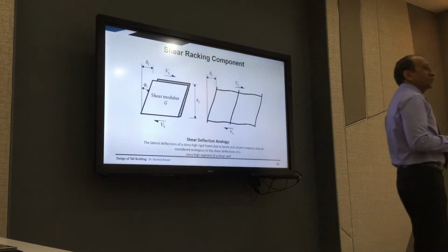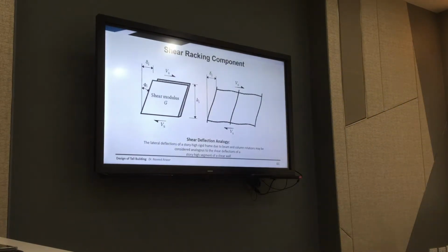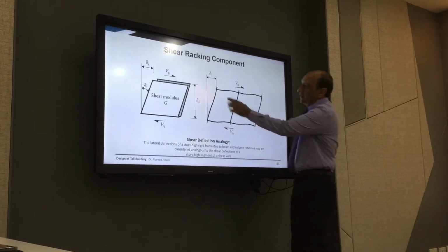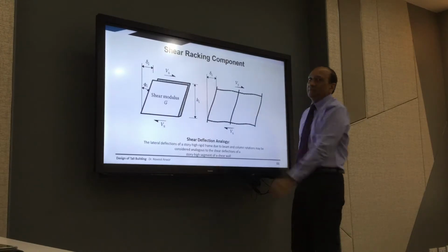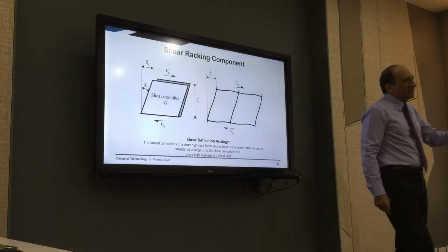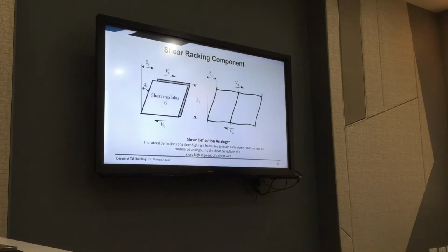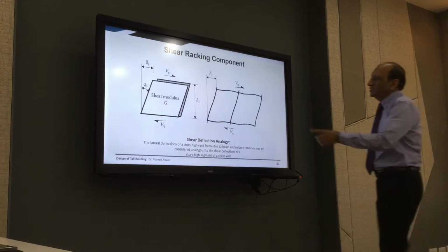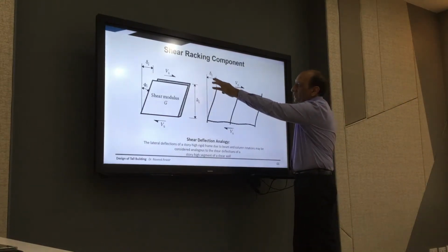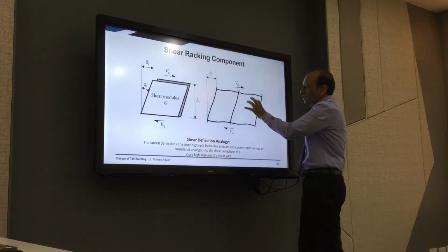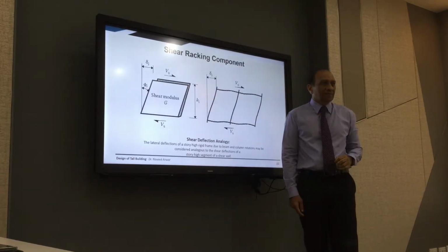This is the main difference between a shear deformation and a flexural deformation. In a flexural deformation, after a displacement, each member in that structure becomes deformed along its entire length, goes through curvature, double curvature, single curvature. Because of that deformation, bending moments are created, shear forces are created, and this displacement is a summation of all the displacements in all the members.